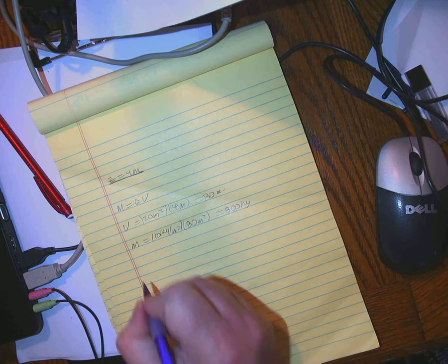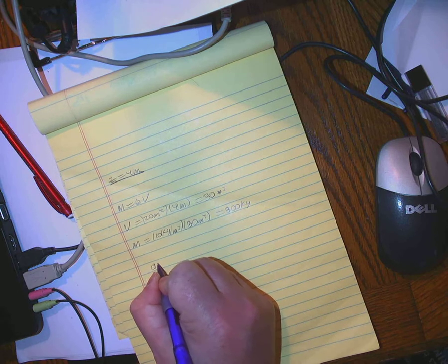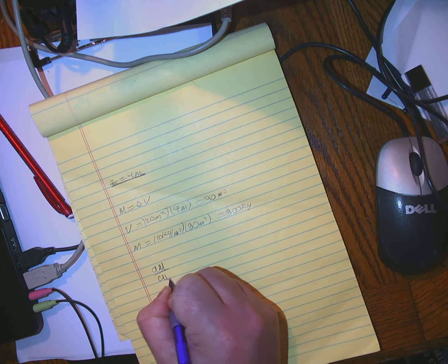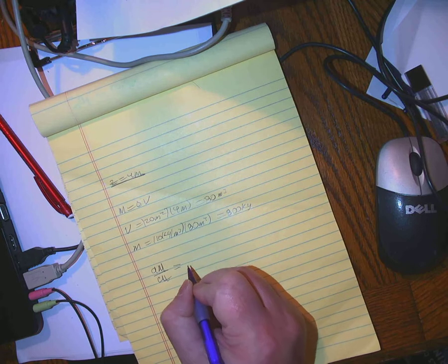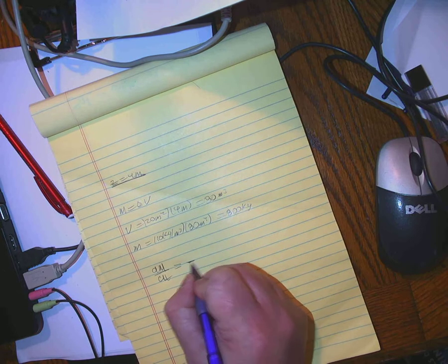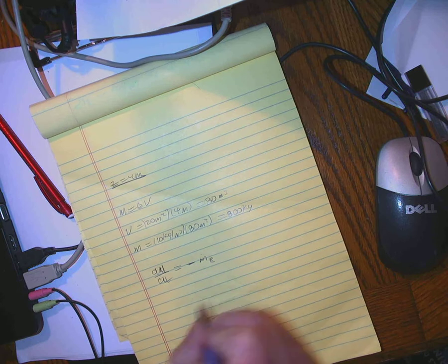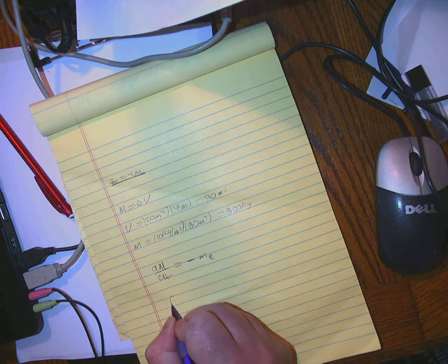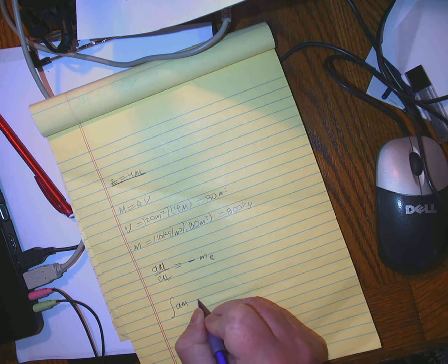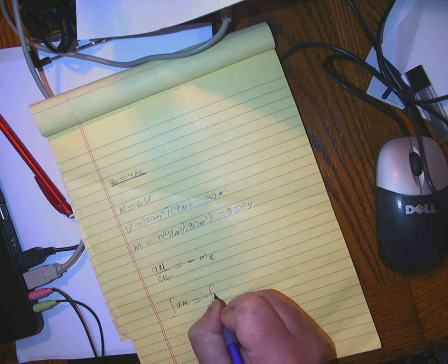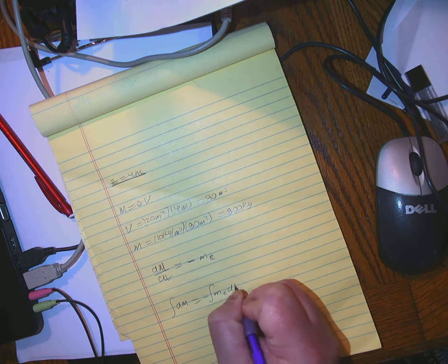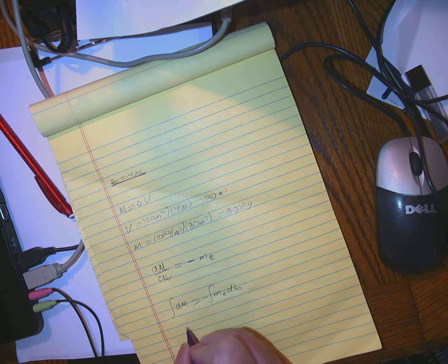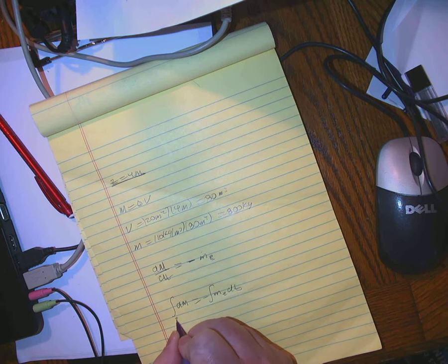So let's set up our general equation. The time rate of change of mass in the control volume is equal to, since there are no inlets, just minus the one exit, m dot E. Separating and integrating, I've got dm equal to minus m dot E dt. My initial mass is 2,500 kilograms.